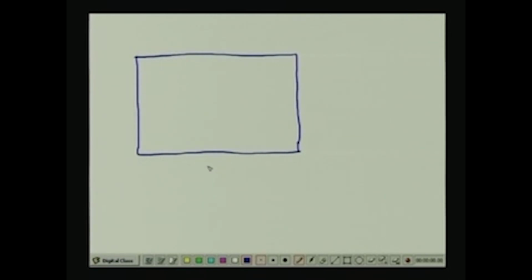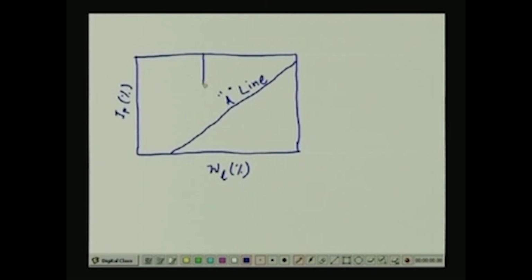What you have here is a plot of liquid limit versus the plasticity index, and you have a diagonal line, that is called Casagrande's A line, and these zones are again subdivided by drawing vertical lines at liquid limits of 35 and 50%. This is actually according to the Indian standard classification system.